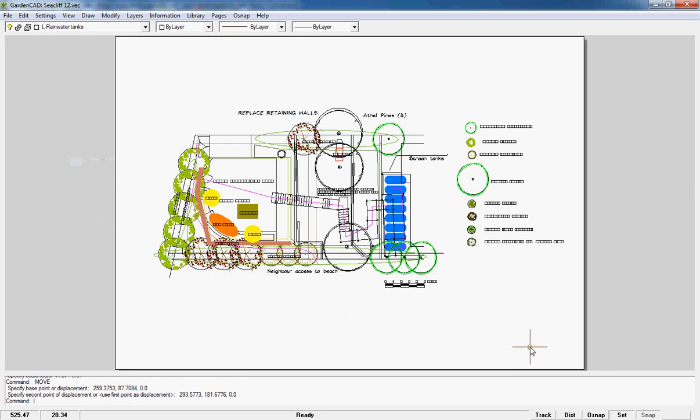So the next stage will be putting my title block down through here. Now 1 to 100 is an approved scale, as is 1 to 50, 1 to 20, 1 to 10. But as you change different size sheets, different scales will work better for you than others. It'll always depend on you and your relationship with your print or copy center as to how you go. So here's a 1 to 100 scale, accurately scaled diagram or plan of our design on an A2 sheet.